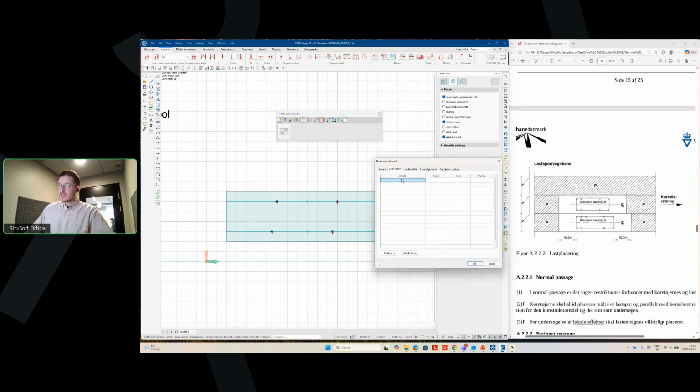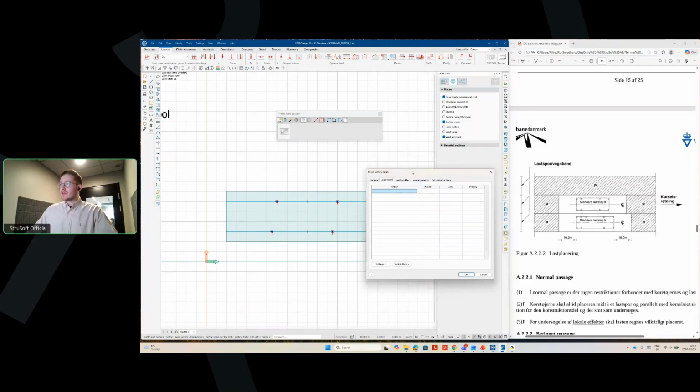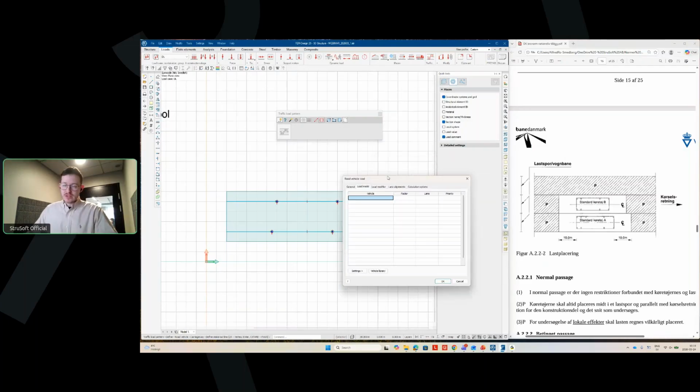Now we can select those in the vehicle list here by simply clicking in one of these squares. And we can find our new vehicles down here. Here you can see I previously did this P, but forgot to remove it. So here we will create the boundary conditions, you can say, for our calculation by putting the different vehicles into different lanes.